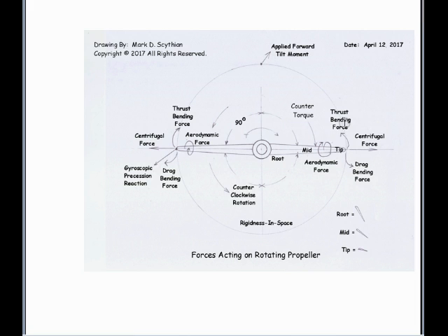Also, the centrifugal force is exploited in order to strengthen the rigid integrity of the blades, canceling out the bending forces. So you'll see some turbofan propeller blades on airliners, and they're actually set up with semi-rigid blade roots, and they'll kind of drag, but as the RPM increases, they tighten up outward from the centrifugal force. So the centrifugal force is also used to help with the rigid integrity of the blade structures by static tensile force outward.